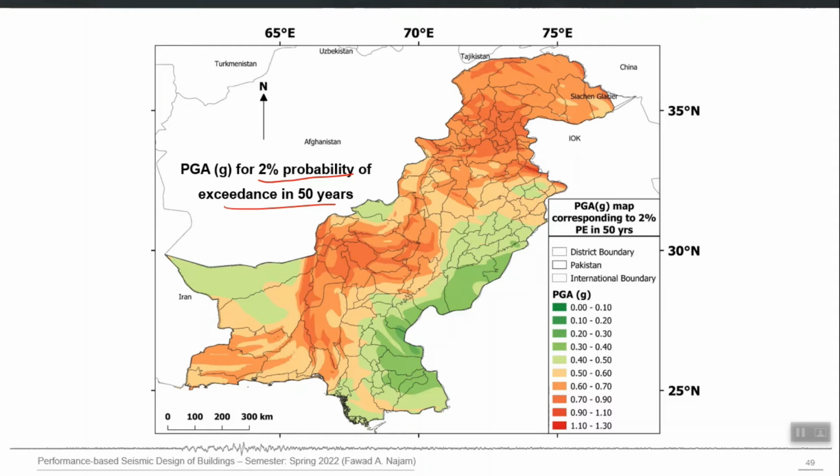So PSHA is an attempt to understand the actual level of seismic hazard. In that attempt there can be continuous improvements. We have more and more sophisticated tools to compute hazard at a particular site, but ultimately whatever method we develop, the past data is the basis for that analysis. The data which is going to be processed and converted into future hazard is actually the past data.